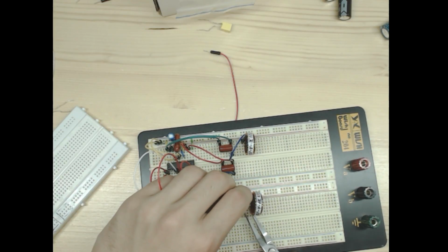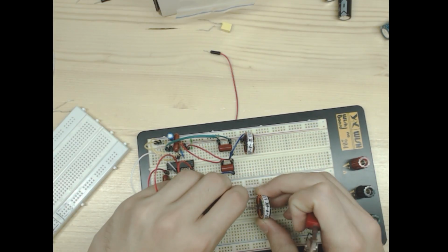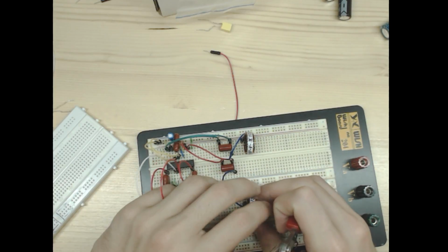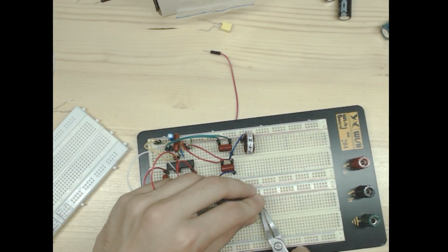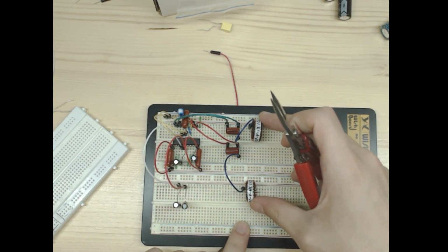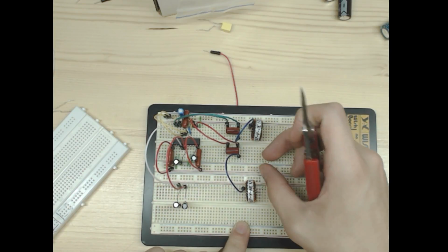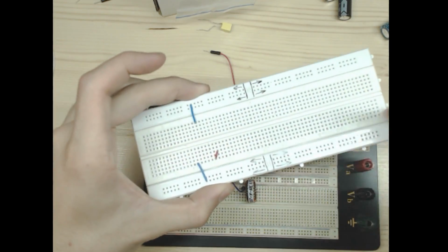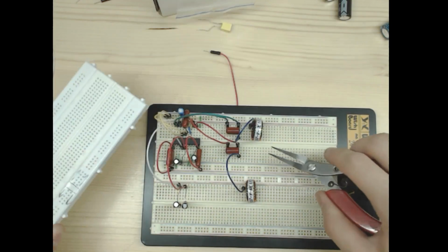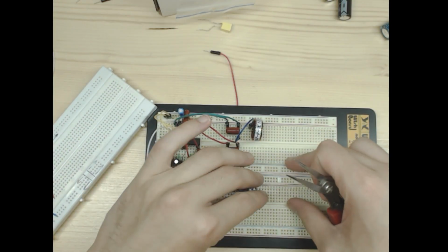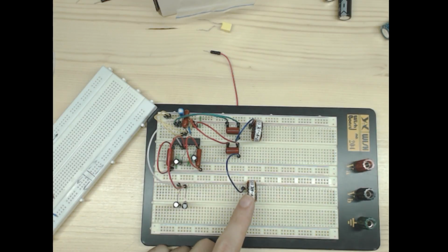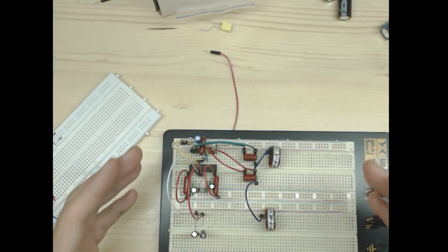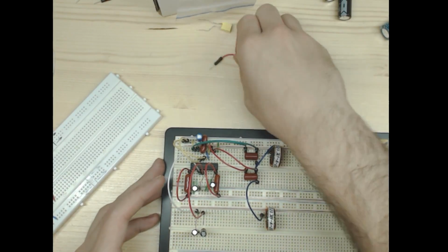I've already had bigger jumpers and it was fine previously, so again, I'm making it smaller than before and on a different breadboard. So I'm going to separate the two inductors because last time they were very close to each other. They were like one was here, one was here. So it would make sense that they could interfere with their own magnetic fields. But we'll see from here if it works any better.